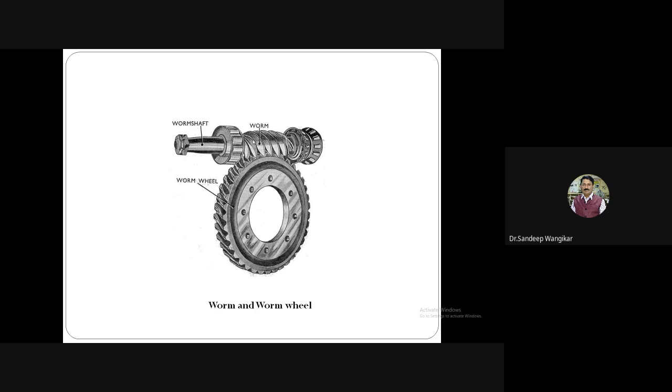But the disadvantage of this case is, in a generalized constraint, that for the last three gears we have seen, it is not required to consider the friction between the mating teeth, the heat generated due to the friction, and the heat dissipated, or the coefficient of friction and its effect on the efficiency of the gear. So all these thermal aspects due to heat generation are required to be taken into account in the case of worm and worm wheel, as there is more friction.